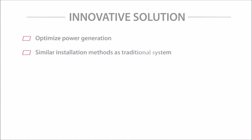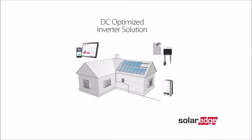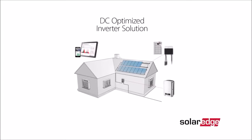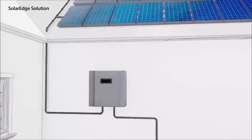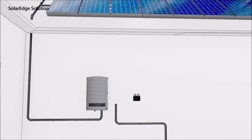When we started to develop the SolarEdge solution, we defined three goals: to optimize power generation of each panel individually, to use the same installation methods and components used to install traditional inverter systems, and to compete with the cost of such systems. Eventually, we developed a topology that meets all of these goals. The SolarEdge DC Optimized Inverter topology combines the best of both worlds. Our solution splits the traditional inverter functionality into two products: the Power Optimizer and a Simplified Inverter.